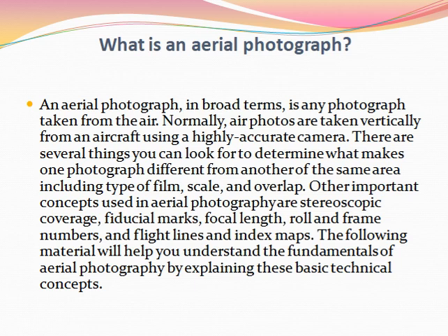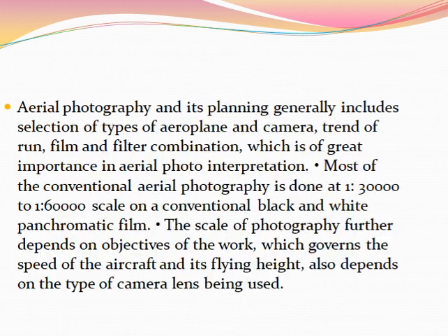Then topo sheets, or topographical maps, are prepared by the Surveyor General of India, Dehradun. In this, the scale used is 1 to 25,000. It shows roads, tracks, streams, water sources along with the contour lines and physiographic features.